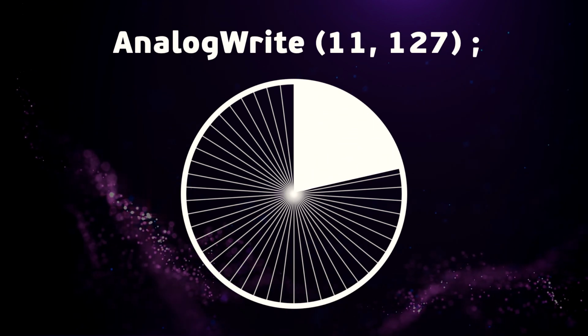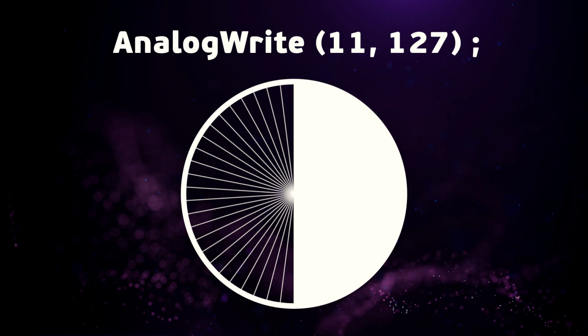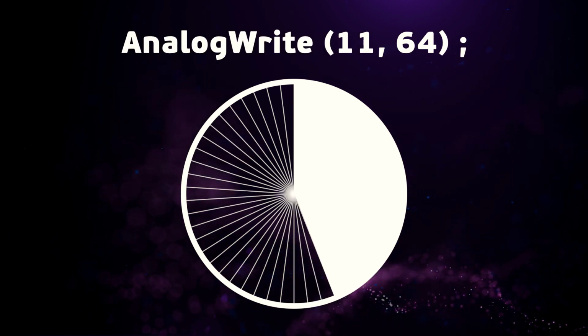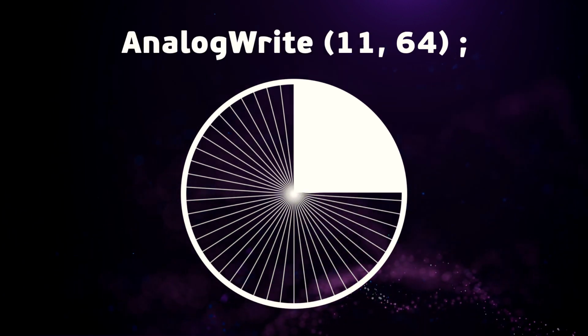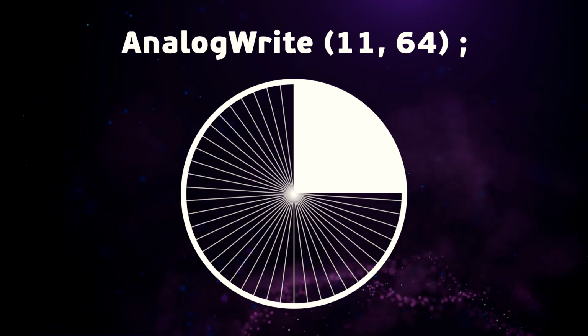127 is approximately half of 255. The LED is half bright. This command makes it quarter bright. The amount of colored sectors is called duty cycle.